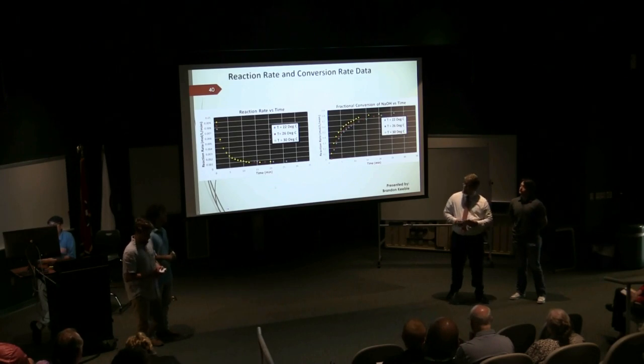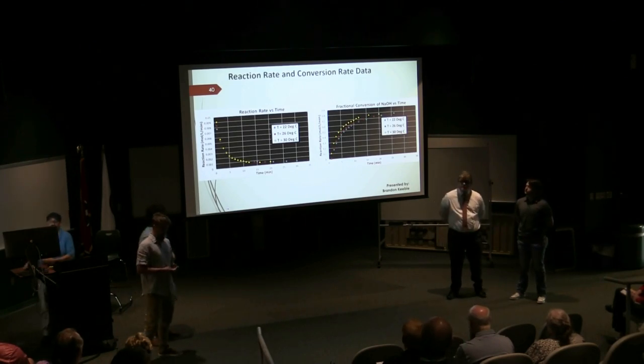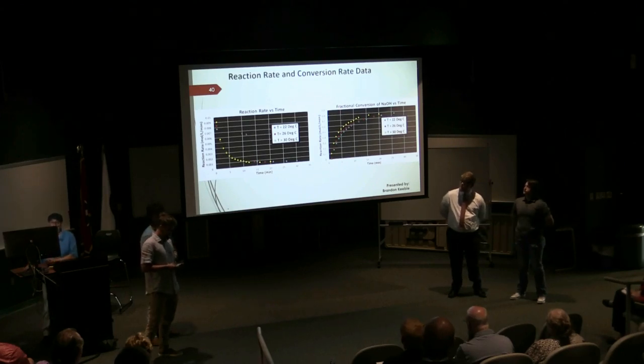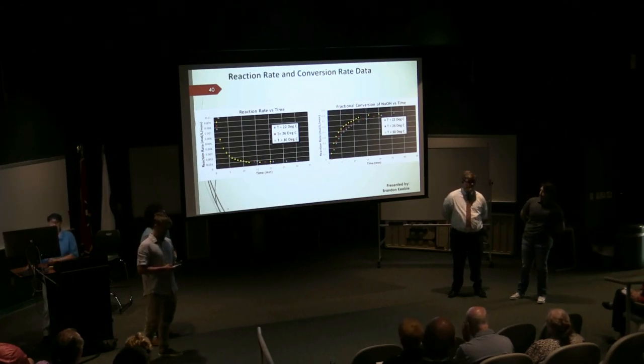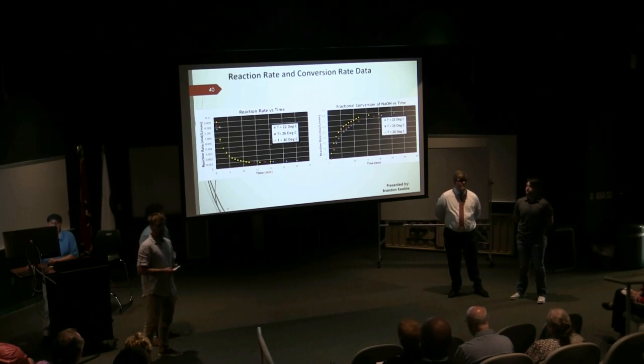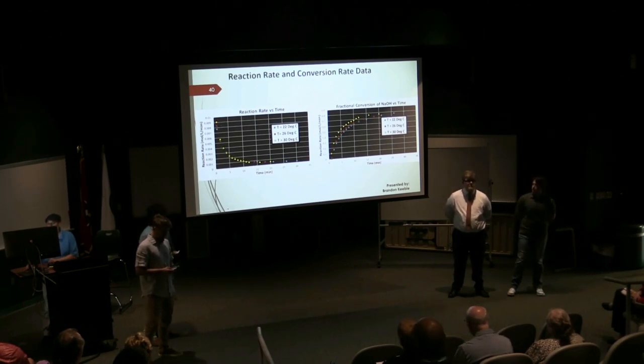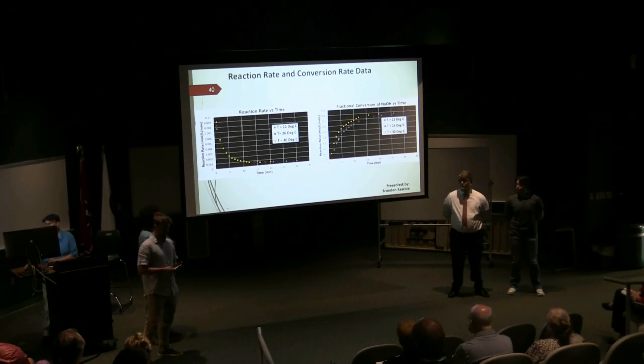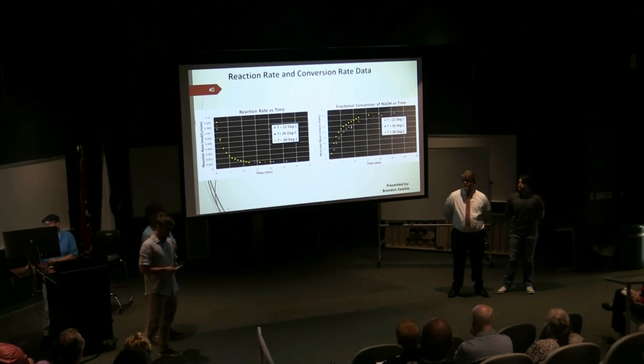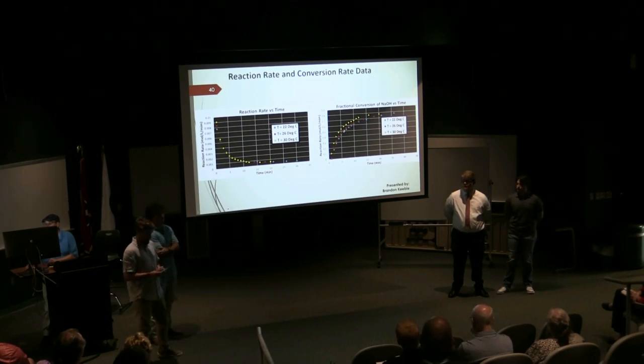On this slide, we're exploring the relationship between reaction rate and conversion rate versus time. Early reaction rate is strongly affected by temperature, and later stages are more influenced by concentration. Most of the conversion occurs within the first 6 to 7 minutes. Higher temperature leads to a higher conversion rate, consistent with the Arrhenius equation prediction.